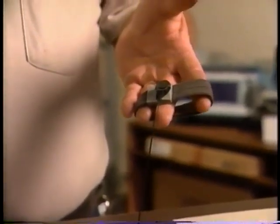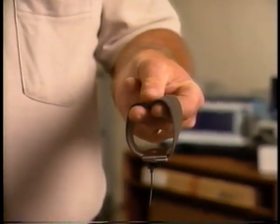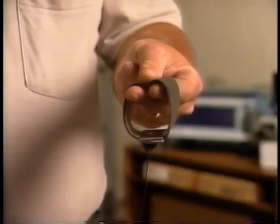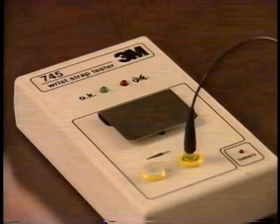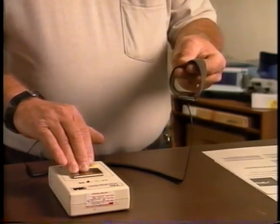Step 3, gently pinch the cuff between your middle and forefingers and thumb while allowing the metal back plate attached to the cord to hang below, making sure you don't let the metal back plate touch your hand at this time. Step 4, using your other hand, plug the banana plug of the cord into the jack on the wrist strap tester. Step 5, with your free hand, press the touch plate and observe the LED indicators.